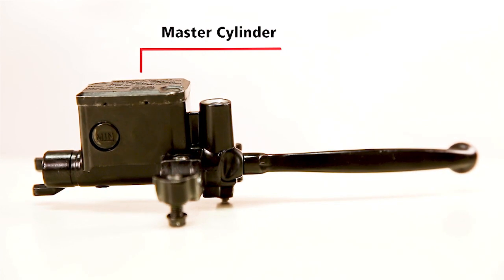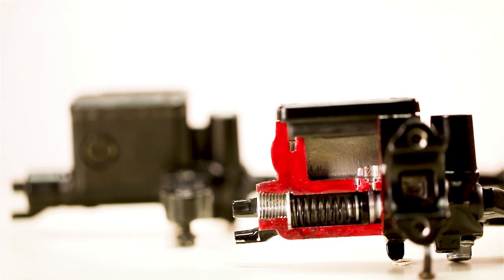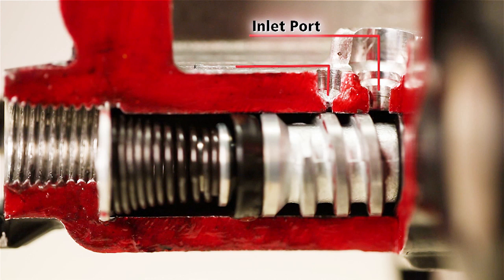Next, let us take a closer look at the master cylinder, which generates hydraulic pressure. The inside of the master cylinder is made up of a cylinder and a reservoir. These two chambers are connected through an inlet port and a return port and are filled with brake fluid.